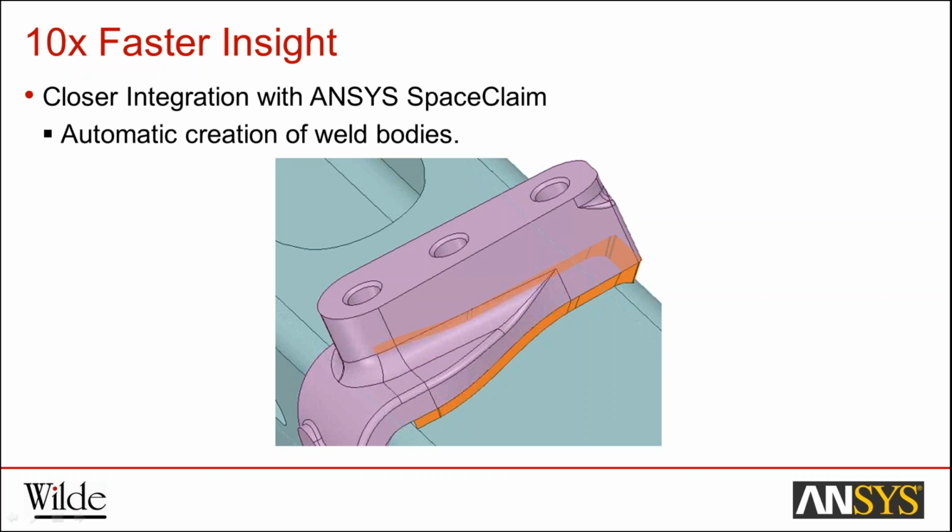And then when we import this into Workbench, the two parts will be mesh connected, so there's no need to define any additional contacts or anything in there. And this is all done, like I mentioned, with this automatic weld body creation tool.